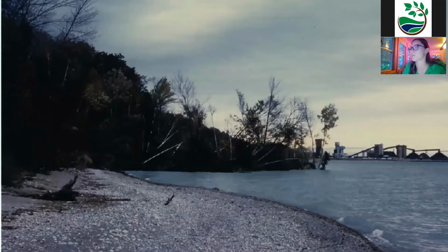And then this is another example, and it's more of a landslide type failure. So you can actually see the salt mine in the background there at Goderich. And so this bank, instead of having a huge chunk slide at once, this one was more of a flowing event. So the bluff got really wet and it started to flow. And just pointing out that in this photo, there are lots of trees on the bluff that failed. So just noting that just because you have a really well vegetated bluff doesn't mean that it will stop erosion from happening. This is just a good example because it's so vegetated.